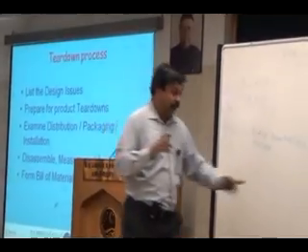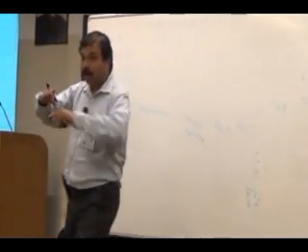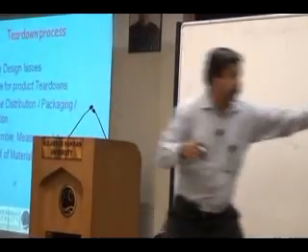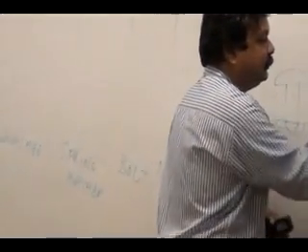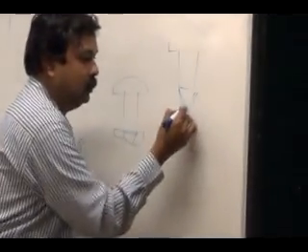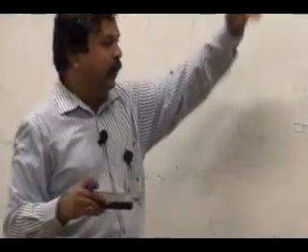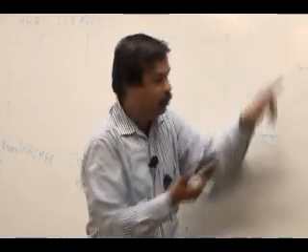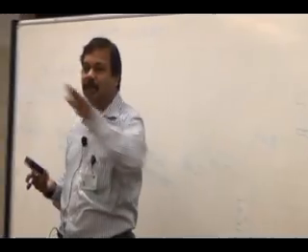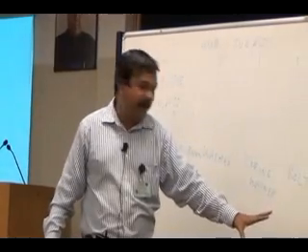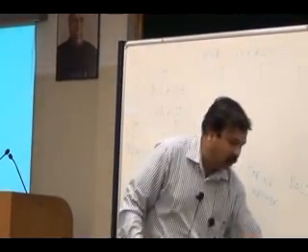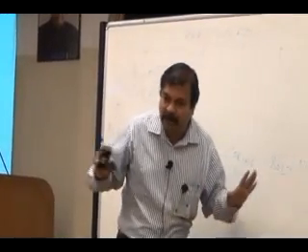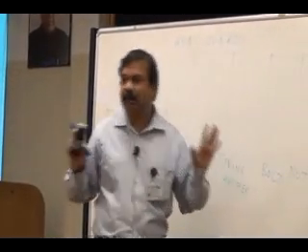Now how is riveting done? You have a hole here, you put the 2 pieces together, put the rivet. The rivet will be something like this. Then there is a riveting tool. The riveting tool will hold from one side and then apply force on the other side. So this part will deform and it will also become like a head. So this is the riveting process. It is a semi-permanent joint. The moment it is assembled, we won't be able to separate them. We won't be able to dismantle them.